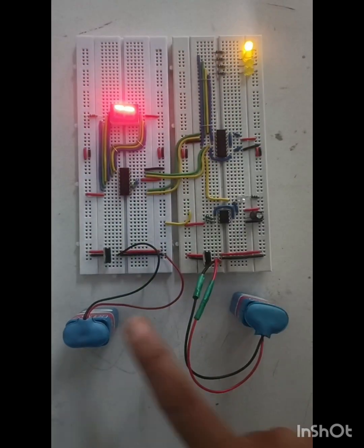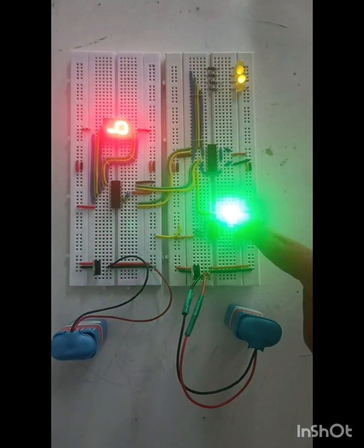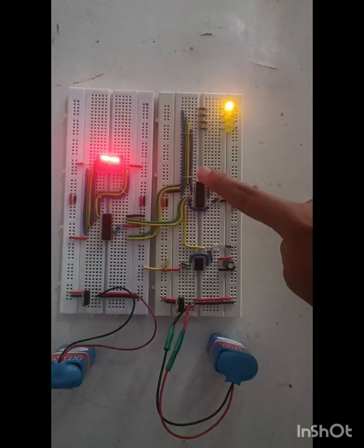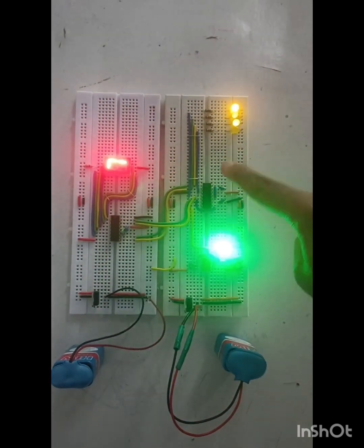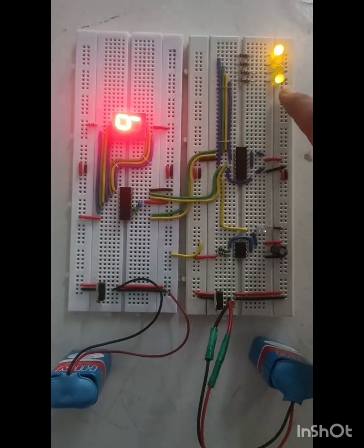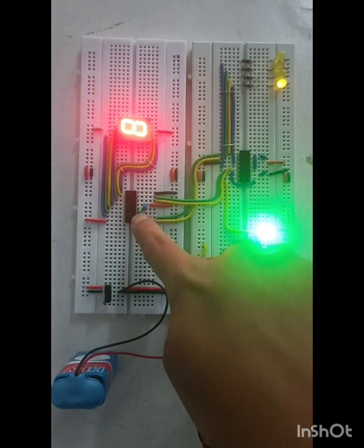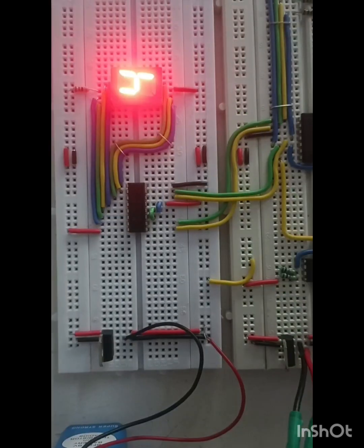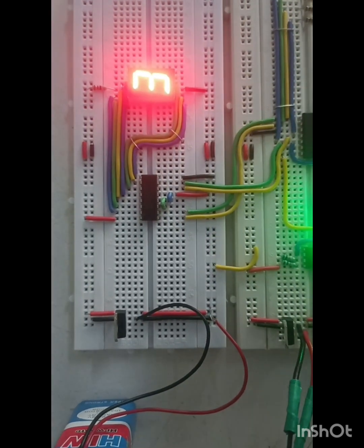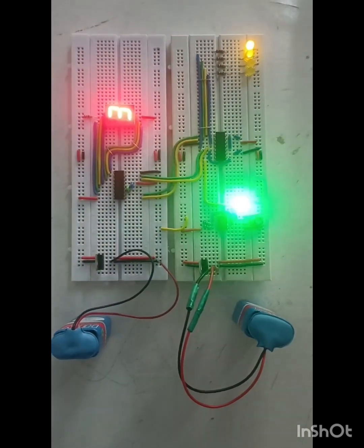We have applied the source of 9 volts to both circuits. The pulse generating circuit generates the pulse, which is displayed by the LED. The pulses are applied to the decade counter circuit, which generates the BCD code shown by the 4 LEDs. The BCD code is applied to the 7 segment display circuit, to the IC 7447 as an input. The 7447 IC generates the necessary signals to activate the appropriate LED segments responsible for displaying the number of pulses